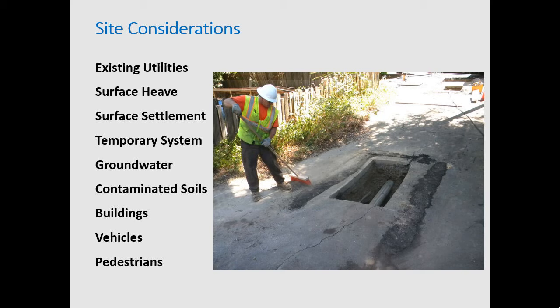You should get a geotech involved and have them help evaluate that zone of influence. But if you're bursting an 8 to a 10 inch, that's up to 17 inches of zone of influence. So any crossing utilities or adjacent utilities or foundations, you're potentially impacting those. I think the calculations may be a little conservative, but we're going to be conservative first, right, as engineers?